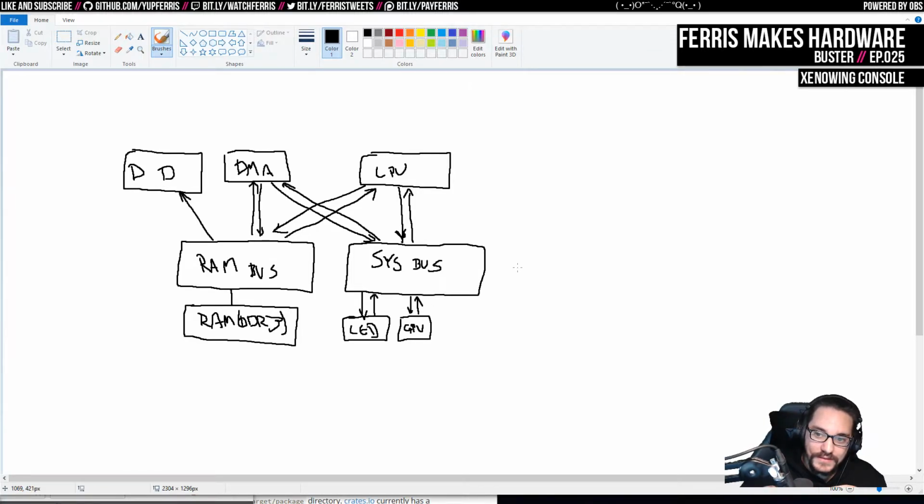And the main thing that this kind of design encapsulates is the fact that each of these buses down here needs to be able to support reads and writes from different bus masters. I think I also need to draw these arrows this way. Actually, yeah, that's correct to do it like that. And then the DMA in particular needs to be able to simultaneously access both of these buses. It needs to be the master for both of these in order for it to move data to and from RAM to these other peripherals here. So the way you're going to move data into the GPU's local memory, it's a tiled renderer, so there's going to be a small amount of memory here.